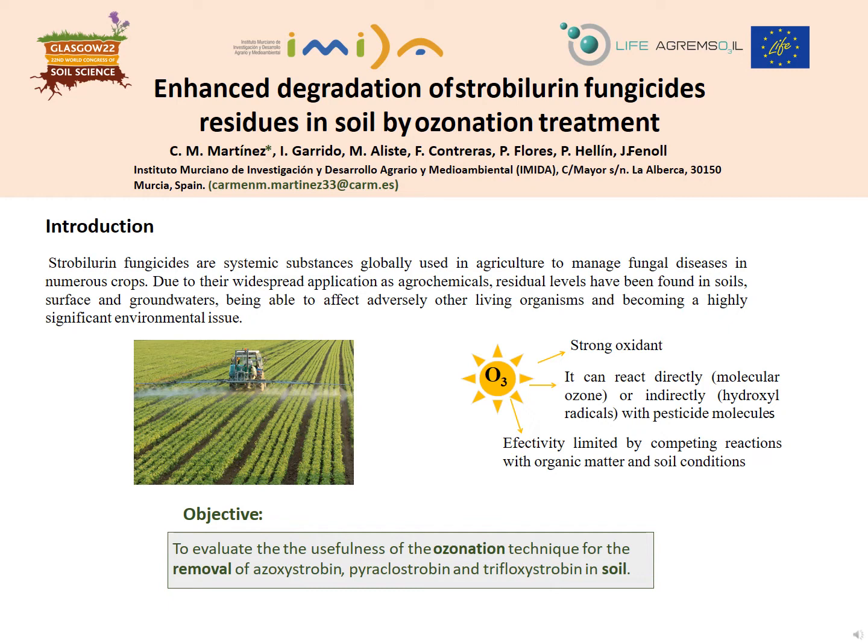Ozonation is a modern advanced oxidation process based on the use of ozone, a strong oxidant agent capable of removing a large variety of organic pollutants. Two main interactions take place during ozonation. Pesticide molecules can directly react with molecular ozone or indirectly with hydroxyl radical, which is a secondary oxidizing agent generated during ozone decomposition. Ozone can also degrade organic matter, decreasing pesticide absorption and favoring their elimination.